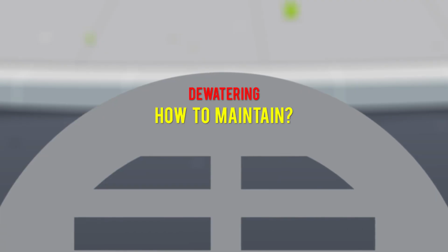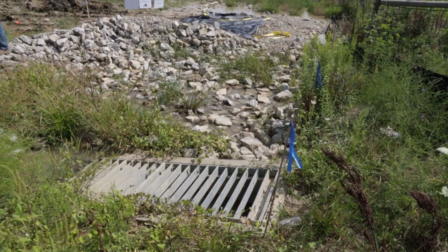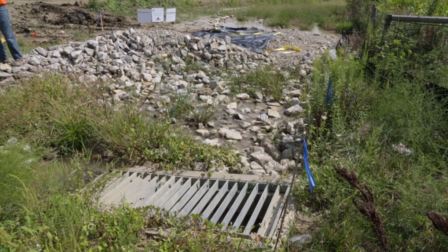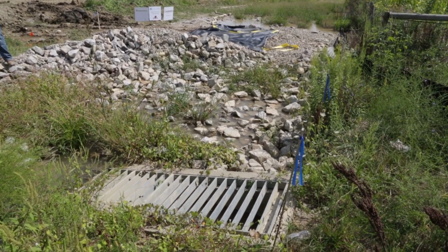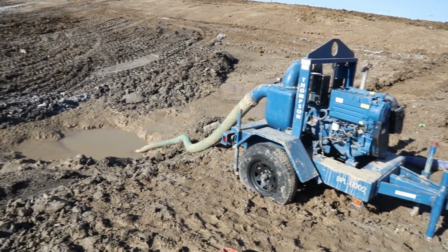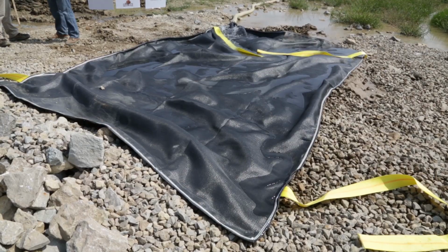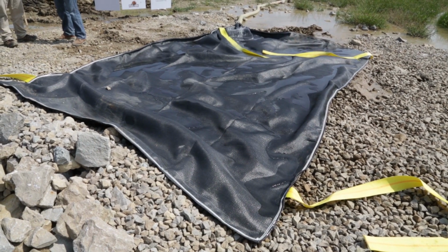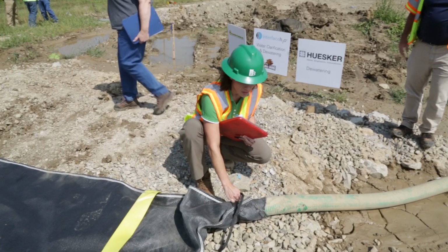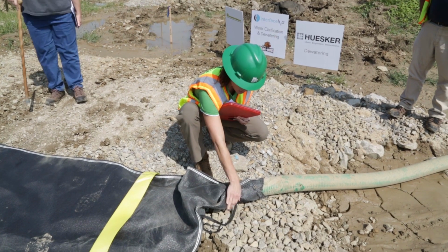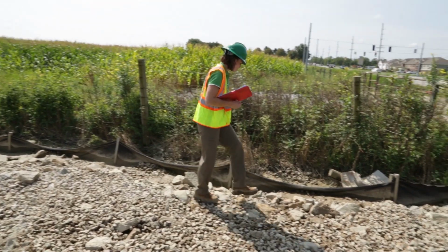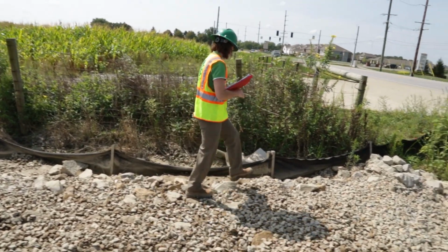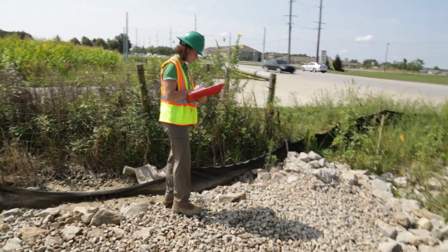How to maintain. Monitor and maintain to ensure the removal of water from the construction site is accomplished in a manner such that erosion and the transporting of sediment and other pollutants are minimized. Dewatering activities shall be accomplished in a manner that the water table water quality is not altered. How to inspect. Check the inlet, check all components for sound operation, check dewatering system to ensure that no erosion is occurring and that sediment transport beyond the construction limits is minimized.